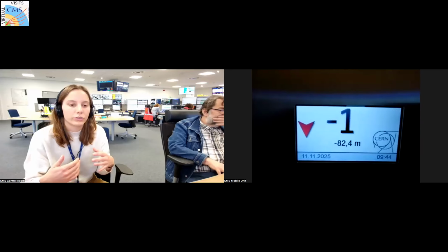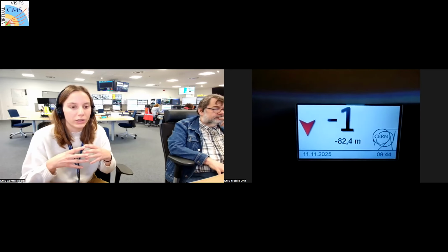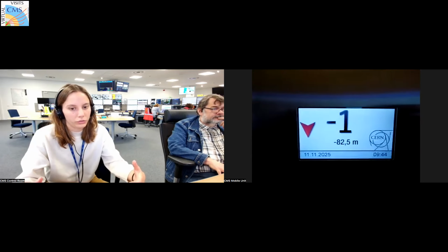The, let's say, trivial one is that stairs for 100 meters is very long. So if there's a very big emergency, probably you don't want to be running 100 meters up. But then there's actually a much better reason, which is that the elevator is pressurized. So there is a slight overpressure inside the elevator. Basically, if there is, let's say, a leakage of any gas that you cannot breathe and is poisonous, this will not enter the elevator because the air will naturally be pushed out of it.